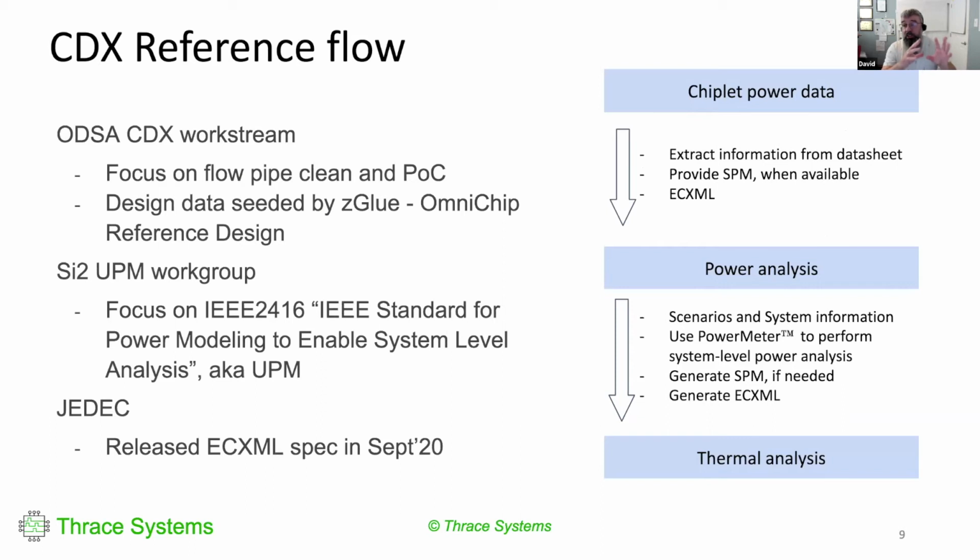We convert those to a system power model, and also for that system we get ECXML format, and see if we can first of all use that description to drive the tools to estimate power for us, merge it with the physical description geometries of what the system is, and merge both together and produce a final thermal analysis. In the tools we wanted to demonstrate what the different scenarios are, how that works at the high level, show the voltage modulation, and feed that into thermal simulation tools.